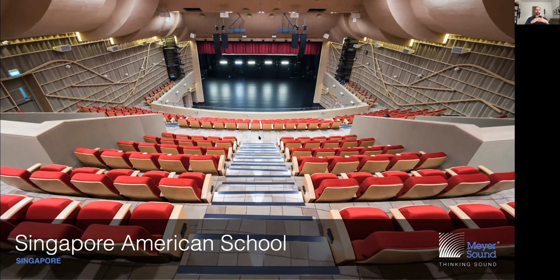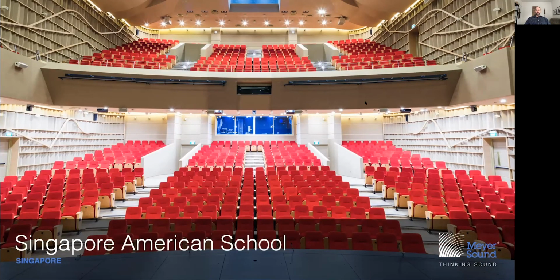So the contrast between the system off and, say, the symphony setting, which is about 2 seconds, is very dramatic. And just another shot here: it has its own under balcony system. What was challenging with this room, since it was an older space, was that we weren't able to attach the speakers directly to the ceiling. So we had to make sure the installer had everything connected all the way up to the structural roof. It's an example of how we can work around construction limitations or weight limitations like that.